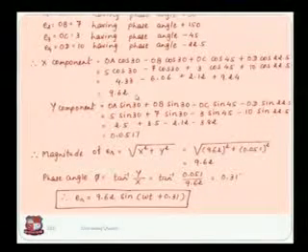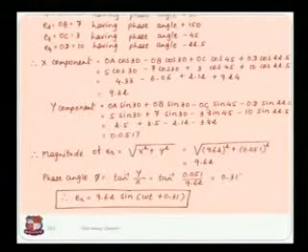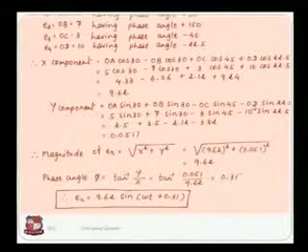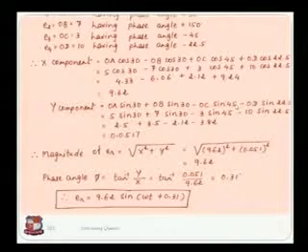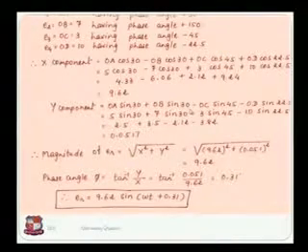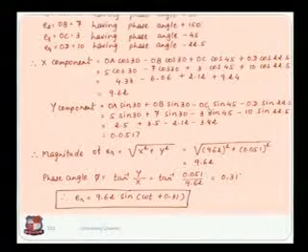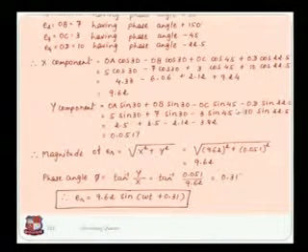9.62. Now for the y component, as we discussed earlier, OC and OD have negative values for the y component. So here it is negative, here it is negative. So your y component is OA sin 30 plus OB sin 30 minus OC sin 45 minus OD sin 22.5.